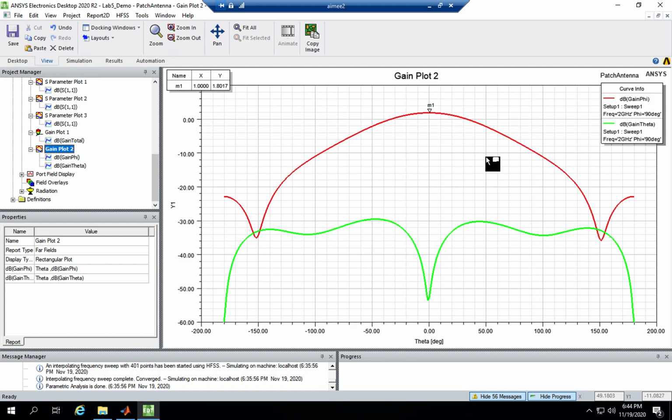So kd sine theta plus beta has to be 0. In order to maximize the radiation, you will set this to 0. You will set the angle that you want to maximize the radiation at, which is the angle theta. And then you have the freedom to choose d and the phase progression. The limitation on d is that it has to be less than lambda in order to avoid grating lobes, which are lobes that can appear in the radiation pattern if the elements are too far apart.